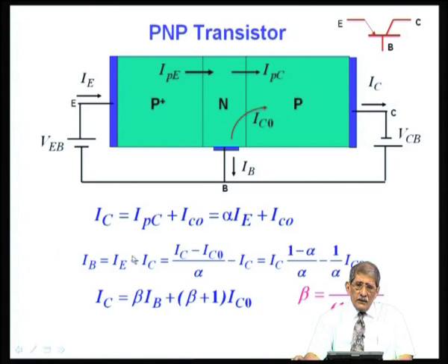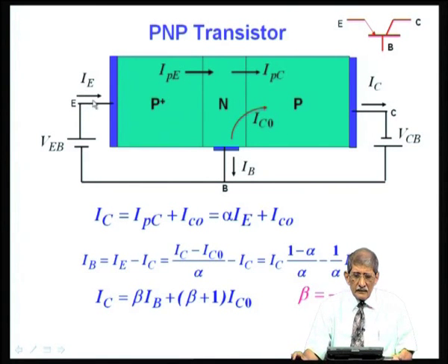Okay. So, now the base current in the transistor, bipolar junction transistor, BJT, is emitter current minus collector current, that is, out of the total emitter current, part of it is diverted to this in the form of recombination current. Okay. So, that is IB is therefore IE minus IC.